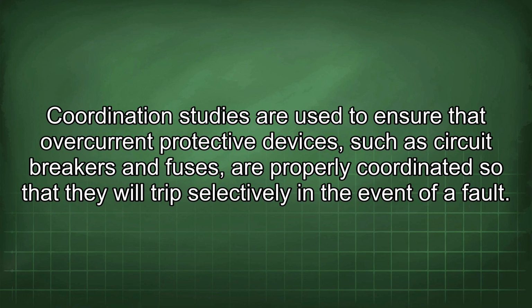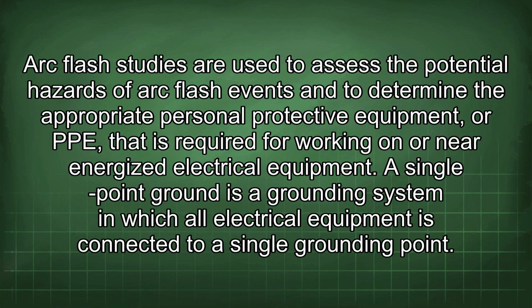Coordination studies are used to ensure that overcurrent protective devices such as circuit breakers and fuses are properly coordinated so that they will trip selectively in the event of a fault. Arc flash studies are used to assess the potential hazards of arc flash events and to determine the appropriate personal protective equipment, or PPE, that is required for working on or near energized electrical equipment.